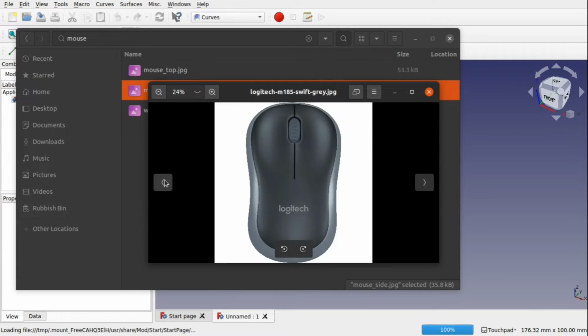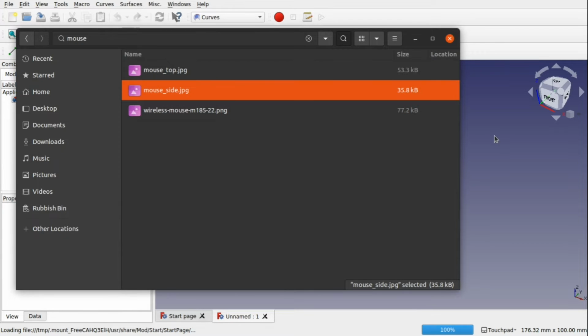So I'll create these as a single sketch. So these curves along here, so one for this one, one for this one. And if we come back and look here, then we can create a couple of sketches for the curves that run across here. And we can create a kind of hybrid curve between those. And what will happen with the hybrid curves, it'll place it in the correct place for where we want it on the model. So it'll place it in the correct orientation and direction, and we can use that to create a NURBS surface across there. And we'll be using these images in our demonstration.